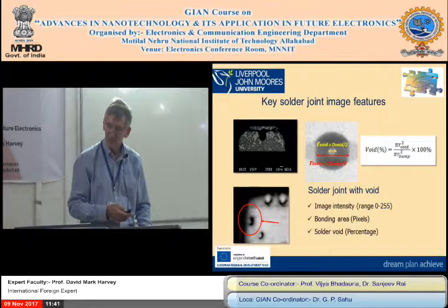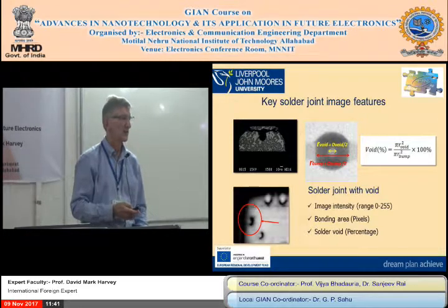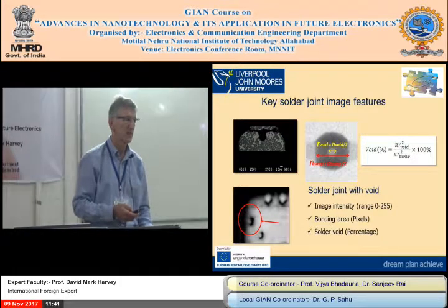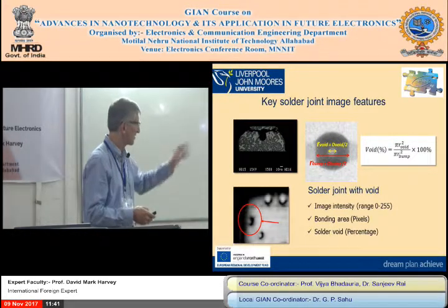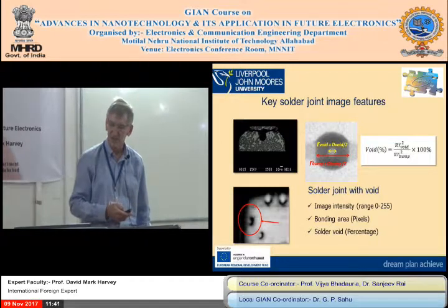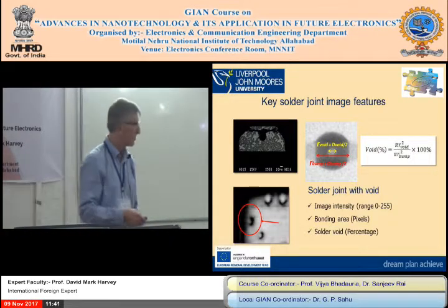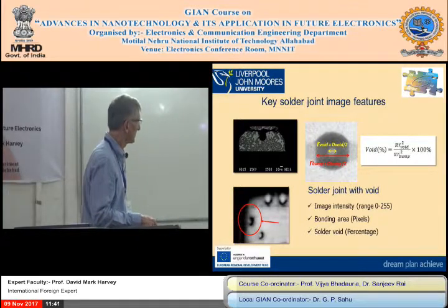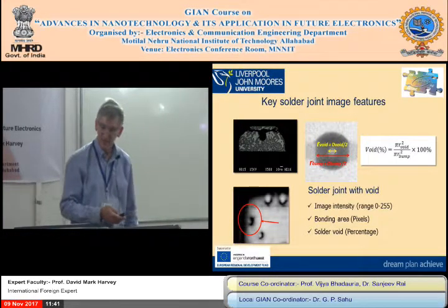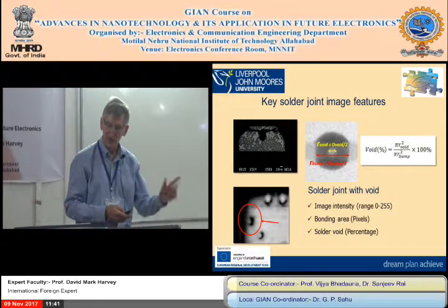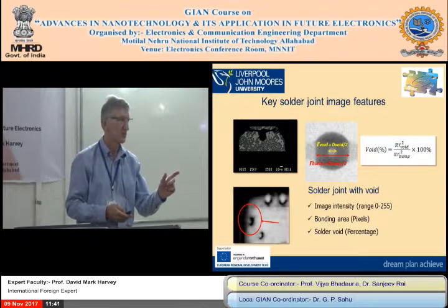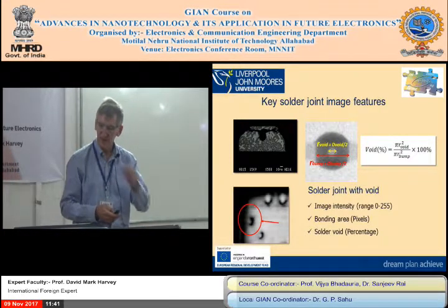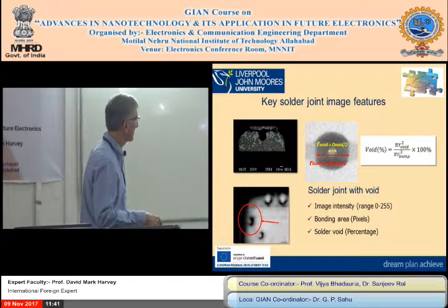So we're looking at the percentage voiding. We came up with a figure for percentage voiding. As you'll see later, if it's more than 3% voiding, which is what that bubble was, it affects the ultrasound image. So there's a blow-up X-ray, that's the typical solder with a void in, and that's what it should look like without a void. The resolution on there is about 1 micron, and those balls across are about 120 microns, just so you have an idea.